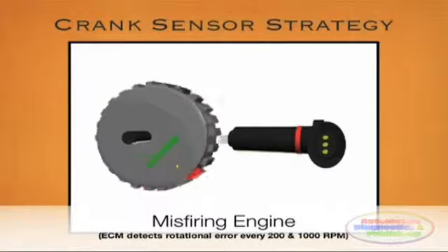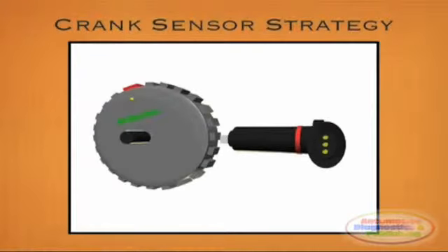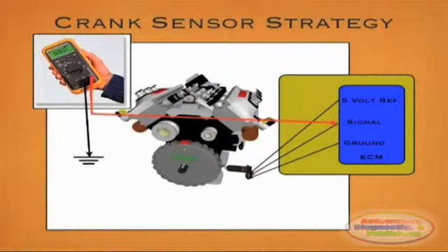There are two basic types of crank sensors: the 2-wire magnetic, or the 3-wire Hall effect sensor. If a scope is not available, a regular multimeter can be used to perform basic diagnostics. Use the meter set to AC or alternating current. You're looking for an output of 3 to 4 volts. Don't confuse this with 2 volts peak to peak, since the meter is going to average the values all the time.